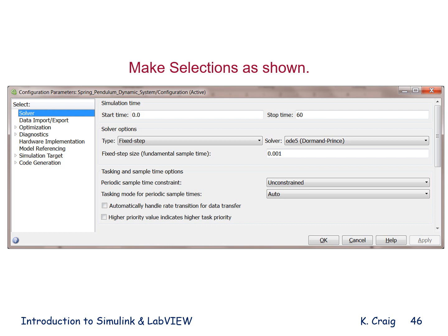I always choose to use a fixed step because if I'm comparing the results of simulations, I always want to have the simulation output given at equal time steps. And I can set up the simulation so each simulation has the same time step. And I do that by picking a fixed step. And I usually pick a millisecond to be the step size, unless for some reason I wish to make it smaller or larger. But in general, I use a millisecond.